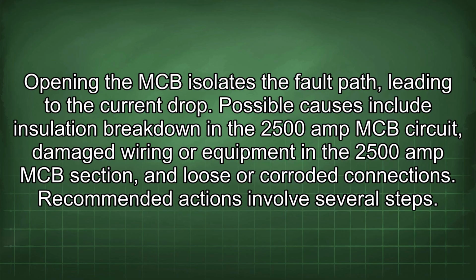Possible causes include insulation breakdown in the 2500 amp MCB circuit, damaged wiring or equipment in the 2500 amp MCB section, and loose or corroded connections. Recommended actions involve several steps.